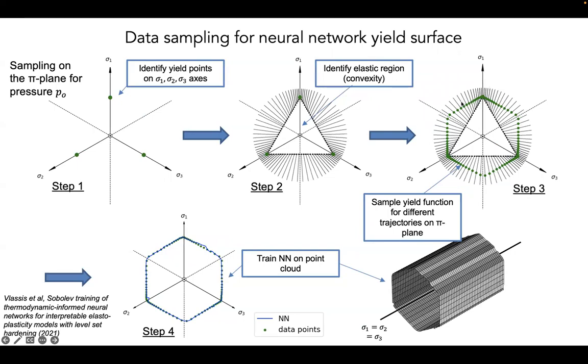Okay, so this is actually a crystal material. Eventually, when it yields, I just stop the loading, and then I take the initial yielding point. So if I get that, then I will have F equal to 0. And then if you try to use this as source data to train a supervised function for the yield surface, what will happen? The yield surface is a function that gives you values everywhere in the domain. Now I'm giving you one contour. So what would happen? Do you understand what I'm saying?